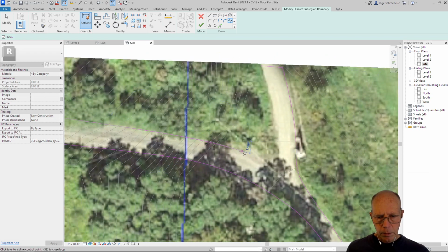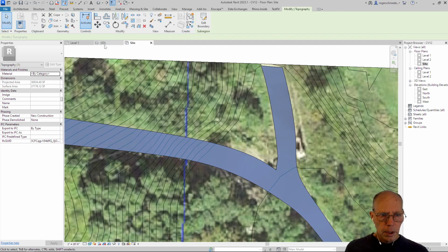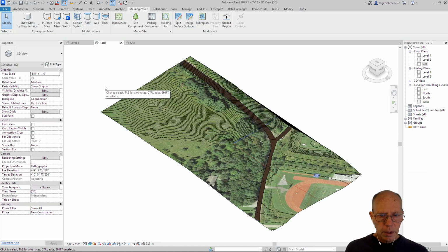And when we get down here, once again, a couple of close points, and then we have that idea that it switches back. So we might actually go to a straight line here just to get us switched back, and then click back to the spline tool, and a couple more points. And once I can get to that other one, I can touch it, and we're completed now. And if we look at it in 3D, now we have that road contoured to that surface.